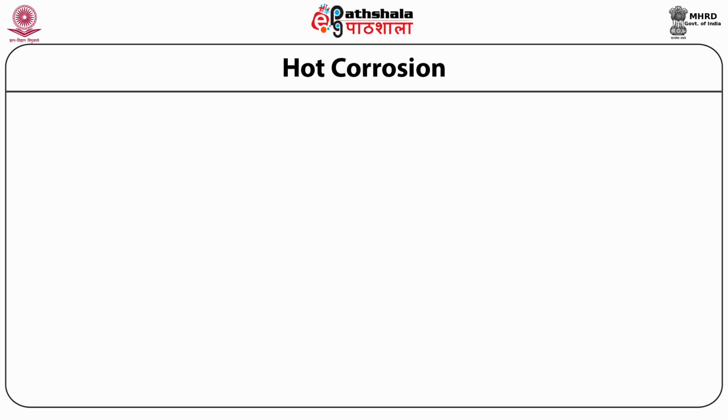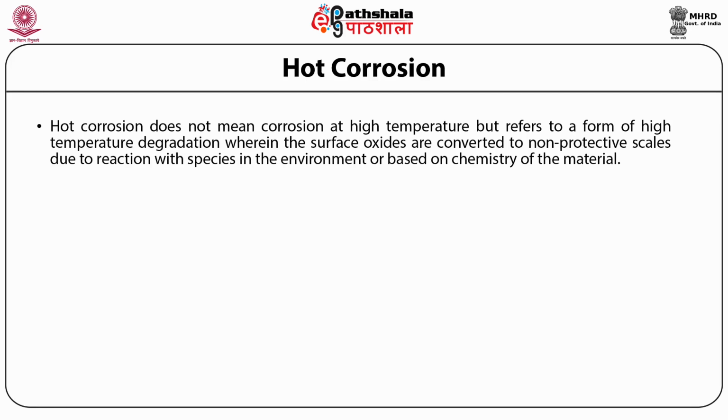Hot corrosion. Hot corrosion does not mean corrosion at higher temperature, but refers to a form of high temperature degradation wherein the surface oxides are converted to non-protective scales due to reaction with species in the environment or based on the chemistry of the material.